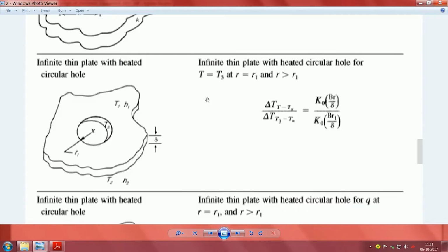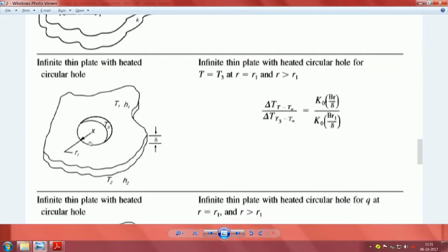And why did I make those things? Because it is easier to mount. Drilling a hole is easy and often it is tapped. Tapped means internal threads are cut. That ensures this whole surface here gets the temperature, and since the stud itself is made out of high conductivity copper, most of the thing will be available here.